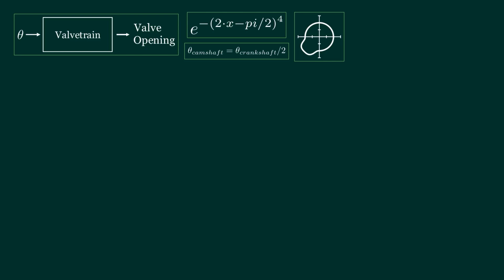If we consider the cam-valve interaction as a mass spring damper system, the valve position can be modeled as a point mass. The blue dot represents the point mass, and the white rectangle is the cam input. When the cam squeezes the valve spring and releases it immediately, it should behave like that. But you notice that the valve goes through the cam, which is not intuitive. To solve that, what we came up with is tracking the position of the rod and cam input to detect whether they come into contact or not. If they are in contact in the following sample, we invert the velocity of the valve in the state vector with respect to the elastic collision.